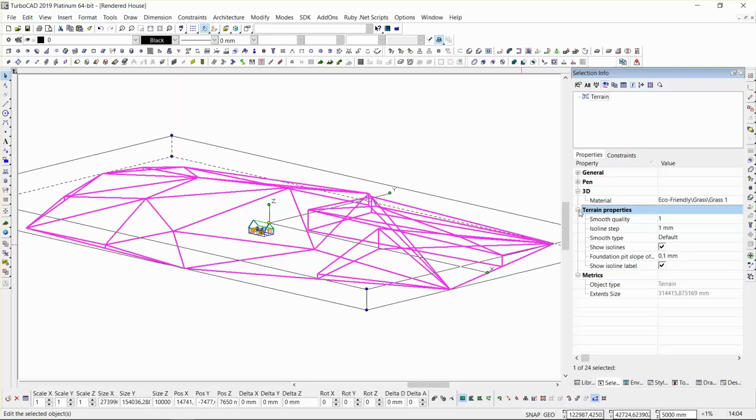Yeah, TurboCAD puts it in. At some stage, import a Google Maps thing. There's a plugin that works with TurboCAD, a Google Maps plugin, where you can import any terrain, either as a map, normal map, or as a 3D terrain with the map overlaid on it. They also got a Google import. Then there's a horizontal one as well. Yeah, topographical Google import. And then it gives you... Yeah, so that you can do in TurboCAD as well, but it's a separate plugin. Yeah. But it's a cheap thing, I think 500 or 600 rand.